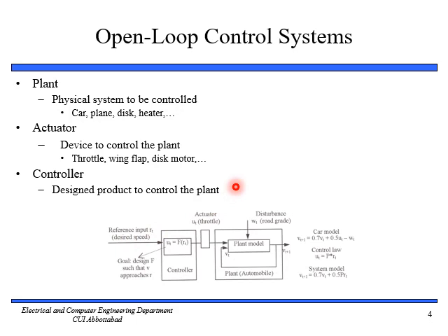And finally we have another parameter, that is disturbance. Disturbance is an additional undesirable input to the plant imposed by the environment that may cause the plant output to differ from what would have been expected. This disturbance can actually change the model, so what we are expecting from the model can be disturbed. For example, wind and road grade are examples of disturbances that can alter the speed of the automobile.